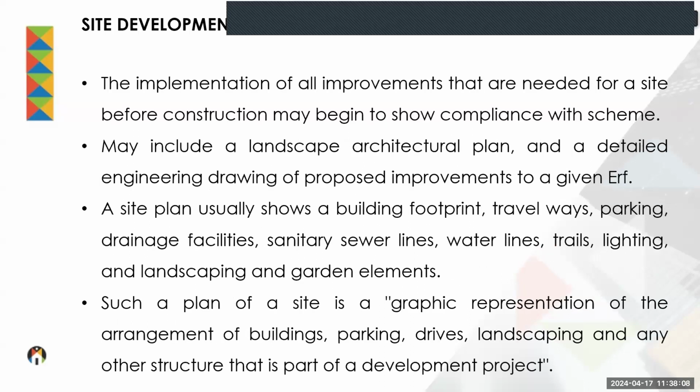Then we come to the site development plan. Now, quite interesting here is that if you go and read some of the town planning schemes, they say that they do not need the site development plan if it's for single residential developments, for instance. I've read one or two that actually say that. So make sure that when you do a building on a property in a town, that you know what is required in terms of the town planning scheme, so that you do not unnecessarily have to comply with requirements where people indeed read the requirements wrong at the local authority themselves.